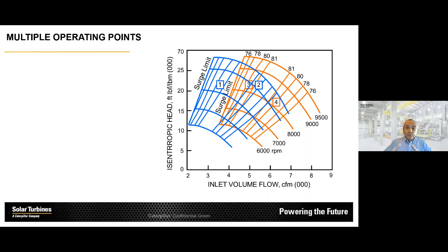And then, of course, when we size these compressors, in general in the oil and gas industry, there is no one design point. You always have to size for different operating conditions. So you have to think a bit about how you best place your compressor map relative to the operating conditions. If I have these 4 operating conditions, you see that I can size a compressor that can run all 4 points without recycling. But that means that my point number 4 is probably not all that efficient. Now, if this is my most important point, then I would use a map that runs my point 4 efficiently, and I would recycle my point number 1. So these are design choices that we take into consideration when we size compressors and pick impellers, to match the machine to the operating conditions.